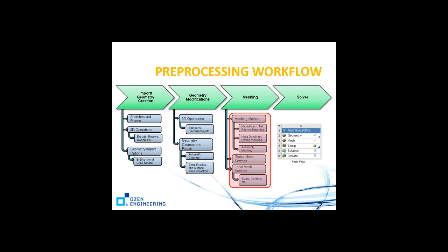Then when we mesh it, as you know, we fill the solid model with a bunch of nodes and elements. So there's another set of idealization of the geometry. And then, of course, once we are done here, either FEA or CFD, we send the mesh into the solver, either CFX or Fluent or ANSYS. It may be rigid body dynamics, or it may be implicit dynamics.